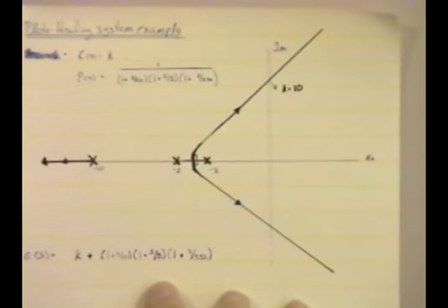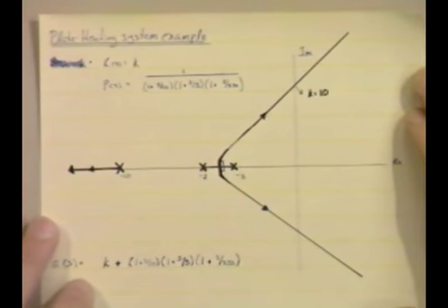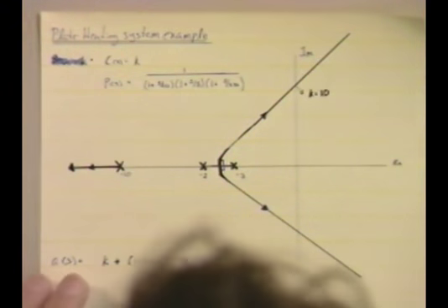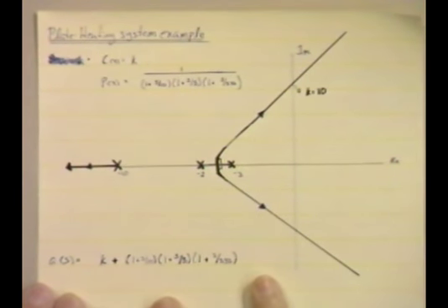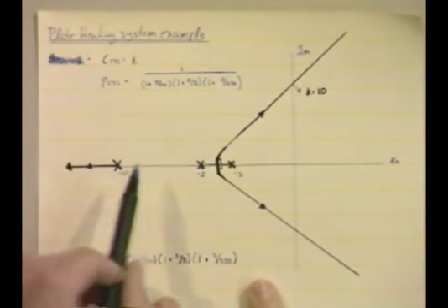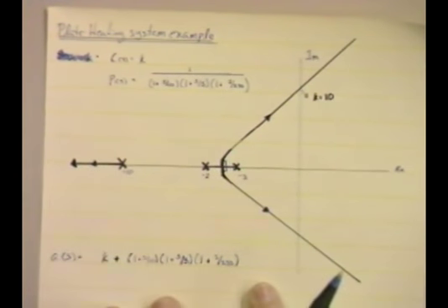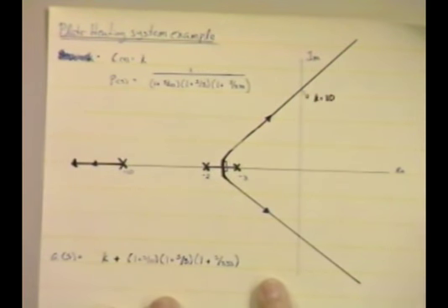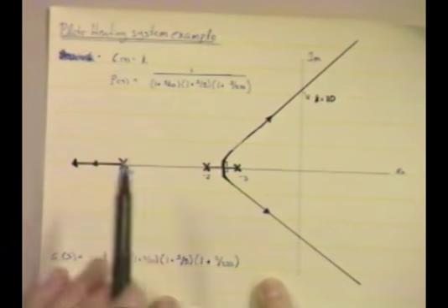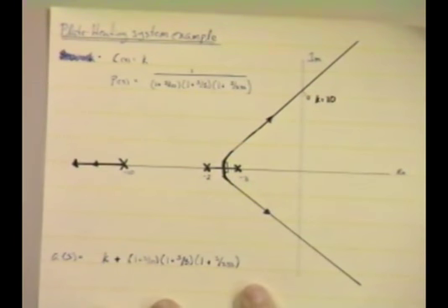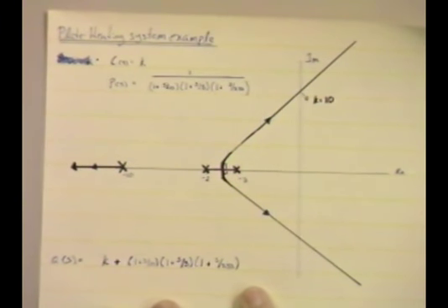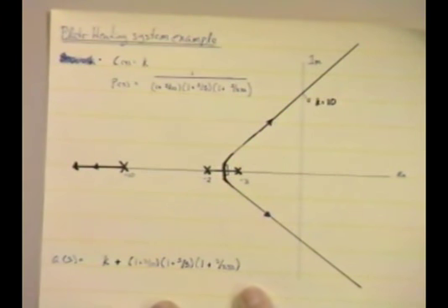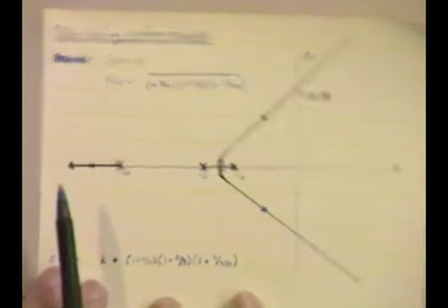It's by doing a root locus, which shows how the poles move as you change the gain. Here I've shown how the roots move for positive gains. So these are the roots of the denominator of the plant transfer function. And if you look at the loop gain, PC, then you would find that these are the poles, of course. And when you close the loop and you look at how the poles have moved as a function of k, this is what you get. It's kind of interesting.